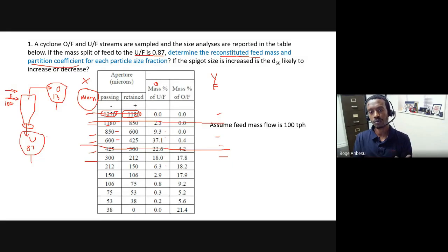So you use dense medium containing 75 micron or 50 micron particles suspended in it, but what we're trying to separate would be particles that are 1 millimeter or 5 millimeters in size from one another. I use dense medium with lots of fine suspended particles, but what I'm trying to separate is coarse, millimeter-sized particles.